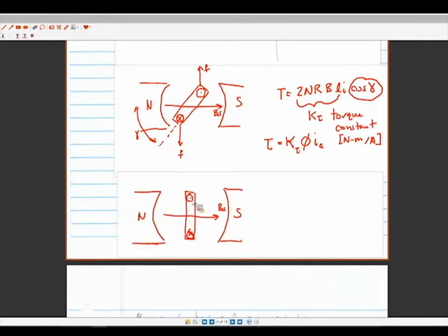So this is the case of alpha equals 90 degrees. Going back to our discussions of back EMF, we said that back EMF, which is the voltage caused in a loop of coil that is moving, is given by N times d phi/dt, where N is the number of coils. Phi is equal to B times A, and A is the area that's interfacing with this B field.